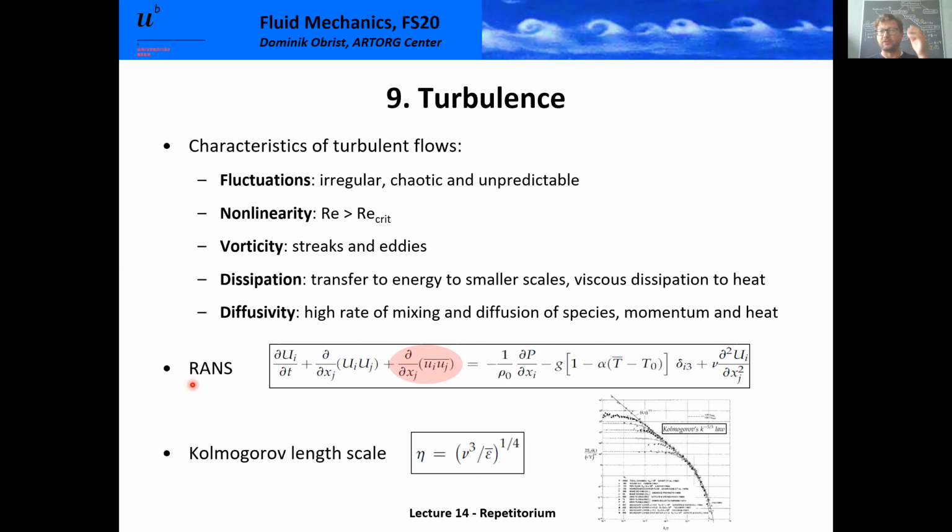Mathematically, we introduced the concept of the Reynolds decomposition. Reynolds averaging, this ensemble average, where we run the same experiment many times and average over the results of many instances of the same experiment. So we get an ensemble average, which is a mean flow. It's not a temporal or a spatial mean, it's an ensemble averaged mean flow, with fluctuations. So we separate it into the capital U for the mean flow, the Reynolds average flow, and the lowercase u for the fluctuations around this mean. We reformulated the Navier-Stokes equations and found equations which look almost like the original Navier-Stokes equations.